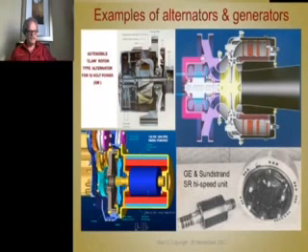This is a gearbox that's driven by some prime mover. This one happened to be a jet engine, also a bigger one than that one. And it drove this gearbox, and there were actually two generators on this, a pair of generators. These are permanent magnet generators with their own bearings. These were surface mount machines, 4-pole machines, 120 to 130 kilowatts at 1800 RPM.